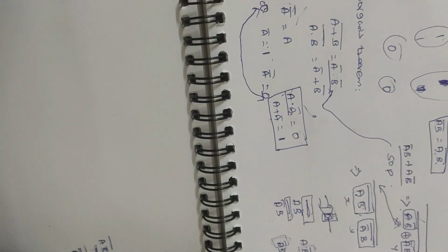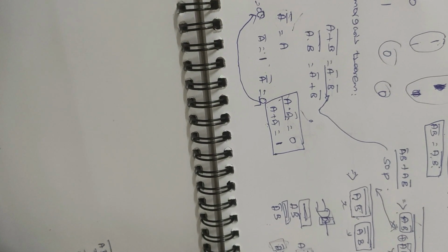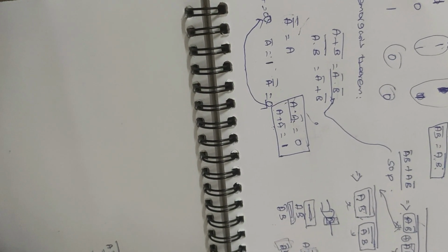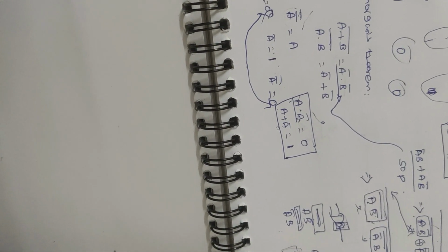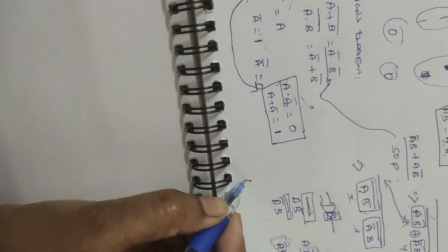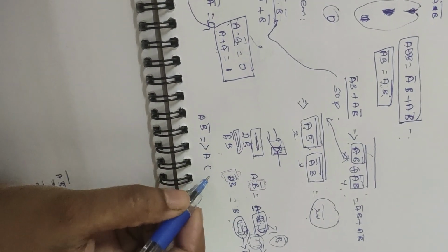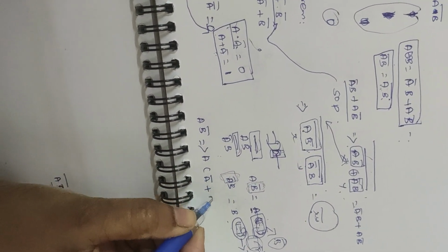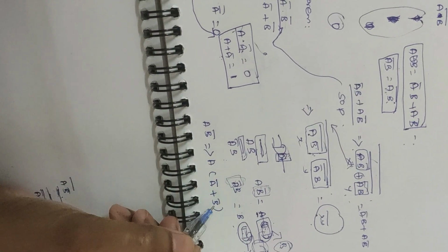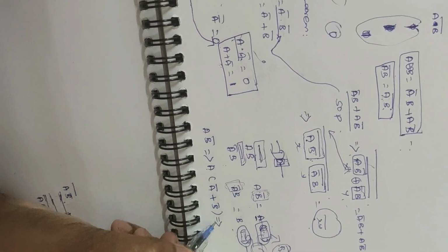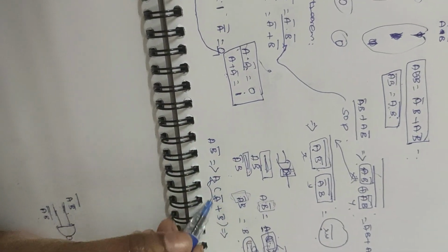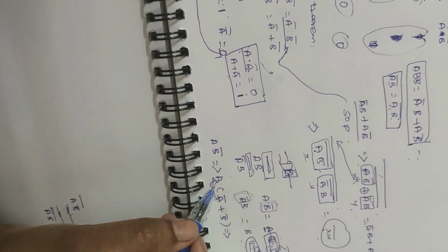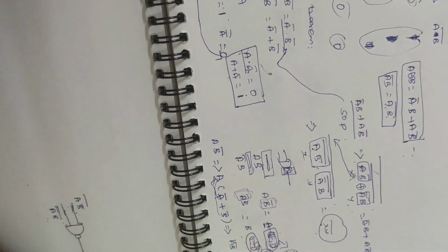So here what we can do, here I am going to give an output as B bar, and here I need A bar. Since I have A here, even if I include A bar here at the OR operation, it won't affect. So for A B bar I am having A inside that, right? If I put A bar plus B bar, because I need B bar here, this will multiply with this. For the A into A bar, as we know, it will be 0. So we need not put 0 in our operation, and A into B bar, so the output will be A into B bar.